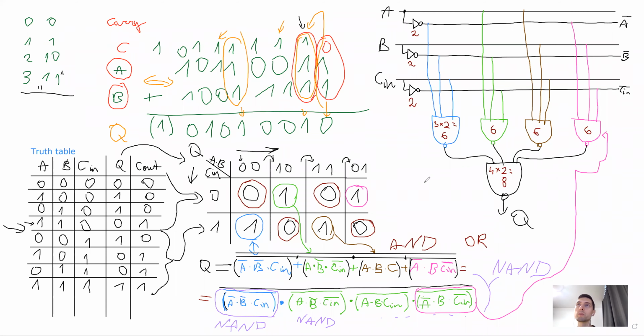So if you said a smaller number because you remembered visually that a NAND gate consists of 4 transistors, for 2 inputs, yes, because 2 inputs each give 2 transistors and you get 4. But in this case, we have 3 inputs, so it's 6. And then we calculate how much it is in total. 8 and 2 is 10, 4 and 6 is 10, so it's 20, 20 plus 12, 20 plus 18 is, I think, 38, something like that, right?